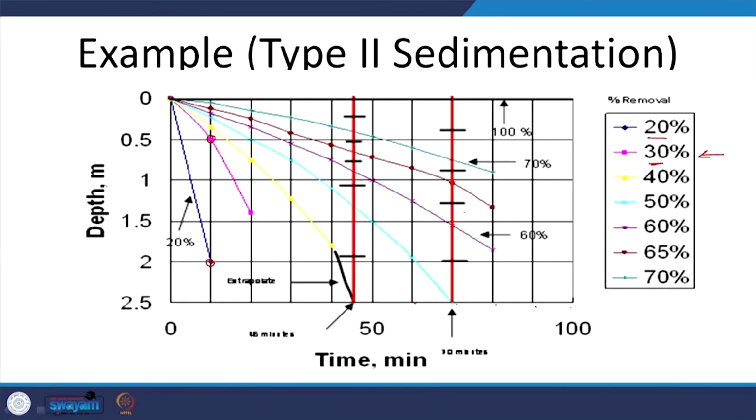So, I plot all these iso concentration lines, ranging from 20 to 80%, and we get this. As we mentioned, we look at this point of intersection and draw a vertical line. This point will be the middle of the point of intersection of these 2 iso concentration lines. This is extrapolation, though, as we have the data only from here.